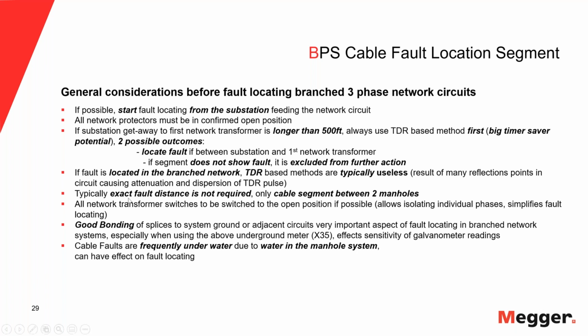One other point that's really very important and sometimes gets a little forgotten is the bonding in these network circuits. In the old days, in every manhole where you had a splice, you had a grounding rod, everything was bonded, was perfect. Today, in many cases, there are no grounding rods anymore in the manholes, or they're abandoned or not replaced because they're so old. But why is bonding important? Because the method we will use looks for basically a current signal, electromagnetic signal.